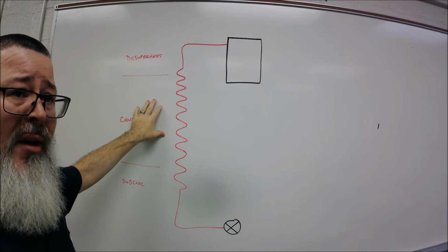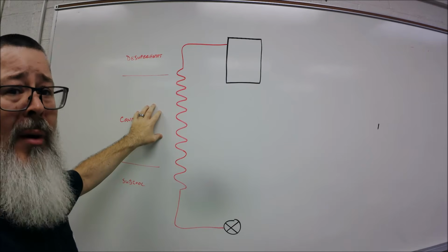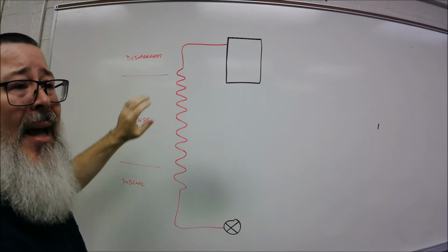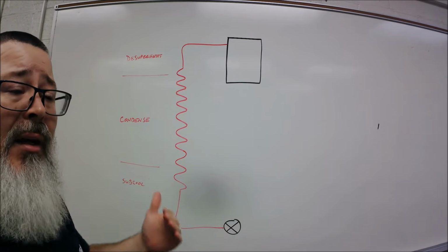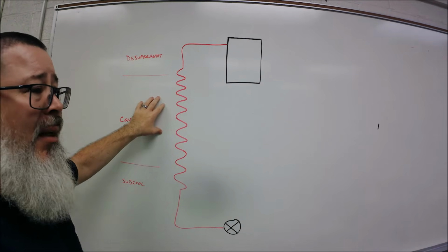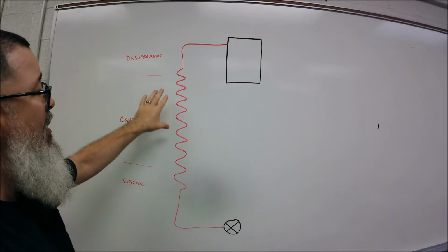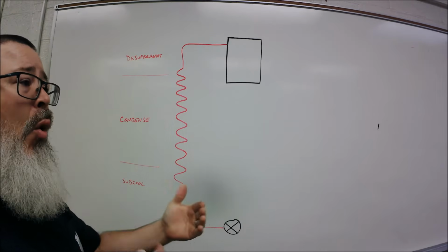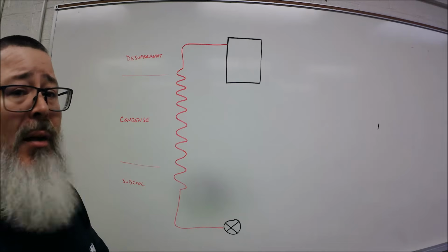It's not a boiling point, it's a saturation point, because on the condenser we don't boil the liquid. We don't have any liquid to boil yet. We are going to cool that vapor down to the point of saturation where we can actually take enough heat out to make liquid. So we de-superheat initially, we get into the condenser, and we're going to cool it down. Same thing as the evaporator. The bulk of the work is going to be done in the coils. We're changing state, and that is where we absorb and reject the most heat.